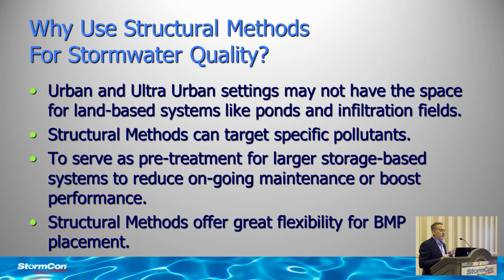Going back to the first bullet point, when you're using structural methods to serve as pre-treatment for your land-based methods, you can greatly reduce the ongoing systems maintenance, and it's really important to try to get as many things out of the flow of stormwater. Think of this as our treatment train effect. Get as many of the gross pollutants and solids out before you start to infiltrate and put them in your underground systems or your ponds. So structural methods are really helpful for pre-treatment.